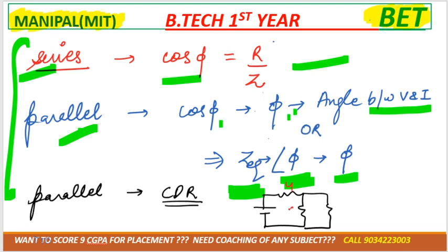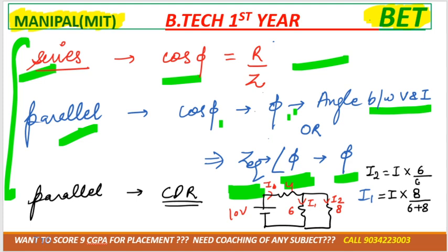Otherwise I'll tell you. Suppose this is 4, 6, 8 and 10 volt. Suppose this is the total current I, this is I1 and this is I2, and we need to calculate the value of I1 using the current division rule. The formula is total current multiplied by the opposite resistance 8, divided by the sum of the resistors connected in parallel, 6 plus 8. Similarly, I2 is the total current I multiplied by the opposite resistance 6 divided by 6 plus 8, right?